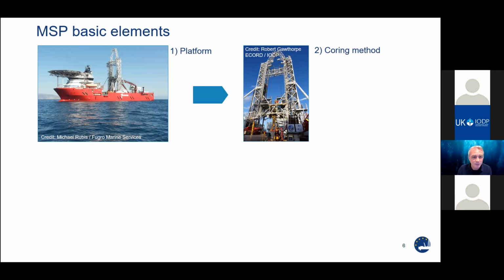The limits of MSP capability are generally determined by one or both of these basic elements. And as you will see later, the minimum water depth tends to be controlled by the platform, while the maximum water depth tends to be controlled by the coring technology. And it is also the coring technology which controls the maximum penetration. So more on that later. Although we can view the platform and the coring method as separate in most cases, so essentially taking a pick and mix approach, we will see later that certain types of vessels are naturally suited for deploying certain coring technologies.